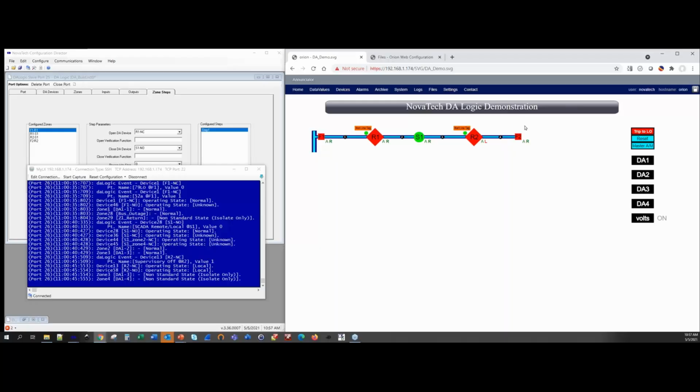All of the devices on the zone on both sides of it are going to be put into limited. Limited says that you can open, but you cannot close. So even though this device is in local, for safety purposes, there's a crew working over in here. Any device can be opened, but it cannot be closed. This device should be blocked and not be able to restore for the safety of your work crews.